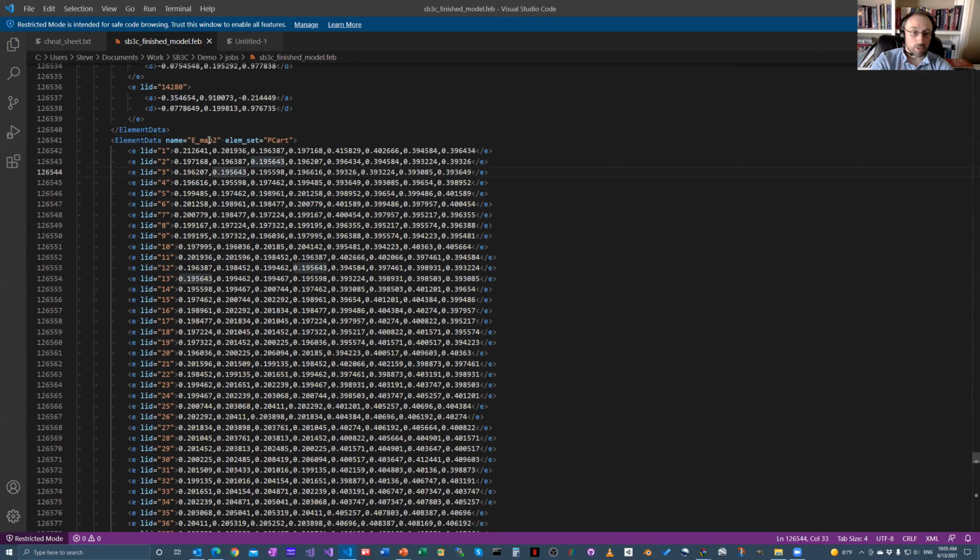It goes in the file as scalar data that assigns a value to each node of that element, right? So there's an 8-node hex, so each element has 8 values associated with each of the nodes.